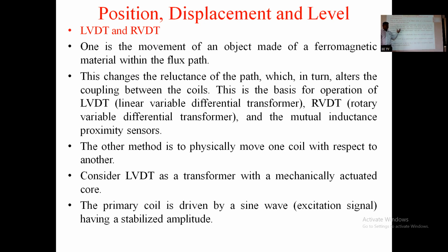Another method has the same construction, but instead of moving that ferromagnetic material, which we can also call the core, instead of moving the core or the material in between, we move the coil. Are you paying attention? If the movement of the coil occurs, that means again the flux linkage to the secondary side will change.